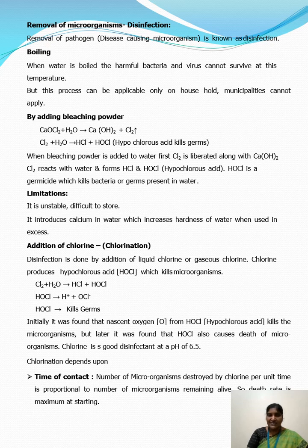Removal of microorganisms can be best done by a process called disinfection. Just now we were talking about a process called boiling. Removal of pathogens, disease-causing microorganisms, is called disinfection. Boiling simply kills the microorganisms present in water. When you keep boiling water for a long time, the harmful bacteria and viruses cannot survive the temperature. This process is applicable only for household or other simple processes. Definitely a municipality cannot employ this method for clearing water of its impurities or killing the microorganisms present in water. So we need to go for better methods.